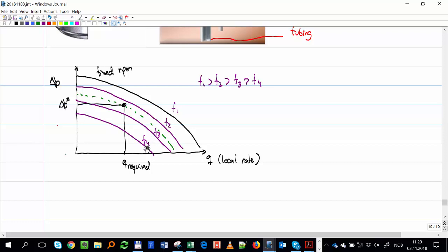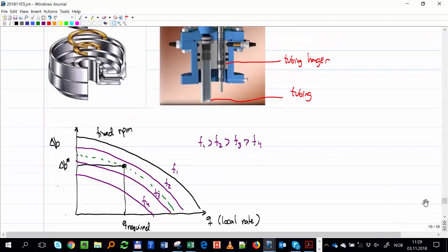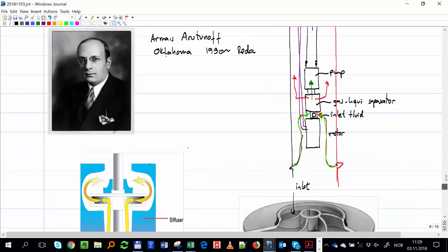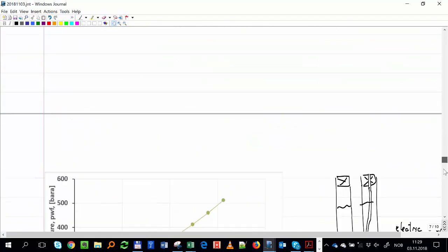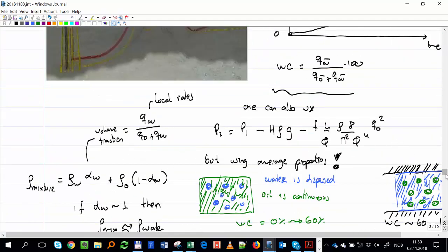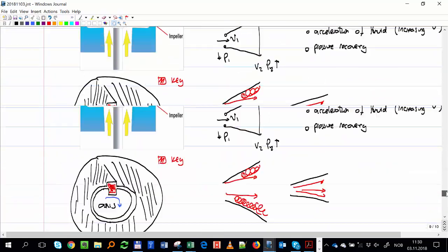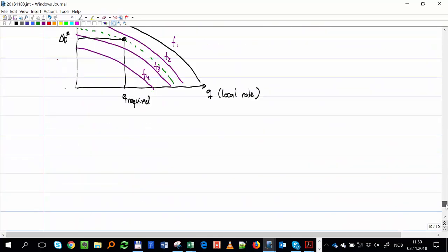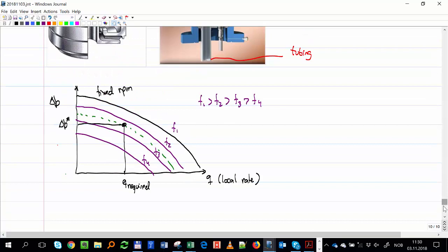So today we covered dry gas choke. We are not going to cover any more choke. For multi-phase, the models are very uncertain, so it's always better to have measurements. But it behaves in a similar way as for gas. And we talked about liquid. What can we do with the liquid equation? It's very useful, but we have to be careful with emulsions. And we are going to talk a bit more about ESP, how they behave, but we are not going to do any exercise, because ESP you're supposed to cover in the advanced course.